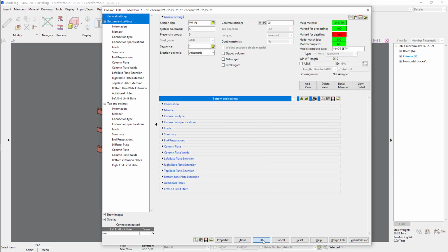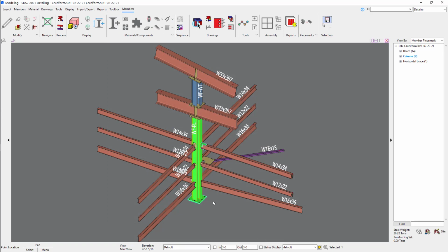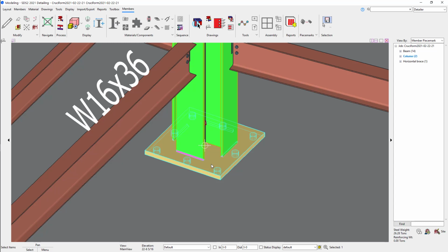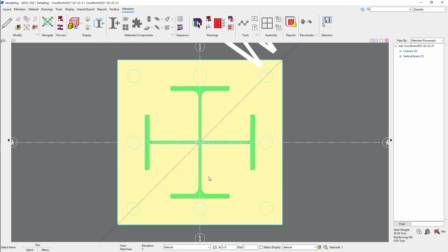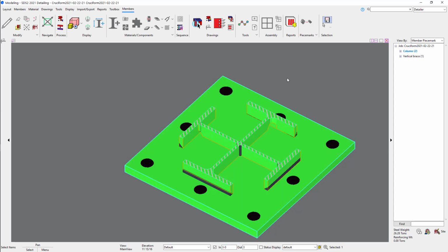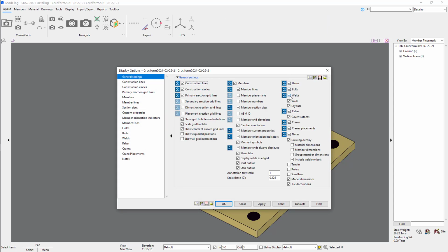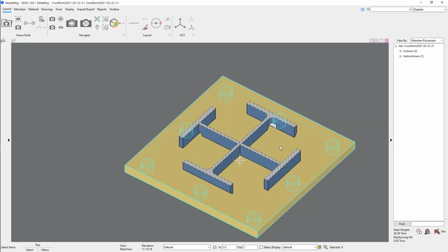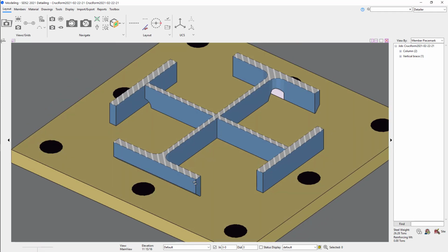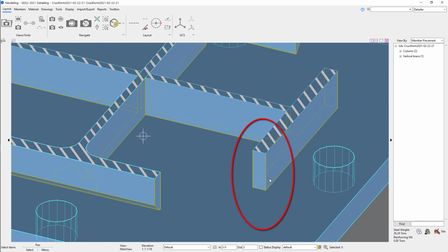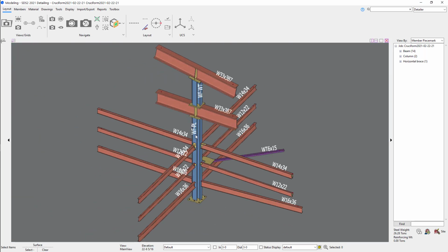Please note that the preparation of flanges made out of plates will not be shown in the model. You won't see the chamfer. This operation is not yet supported. To complete the user base and cap plate welds, I will mention that the welds are not hashed into the piece marks, so the plates will not get different marks due to different weld configuration.